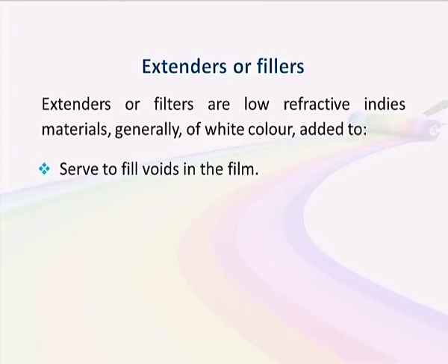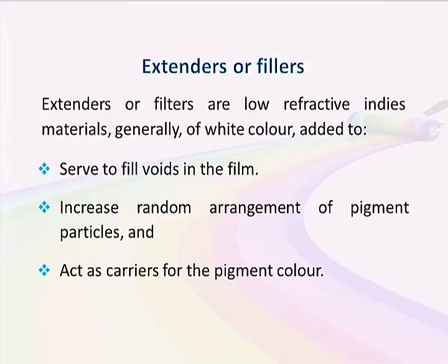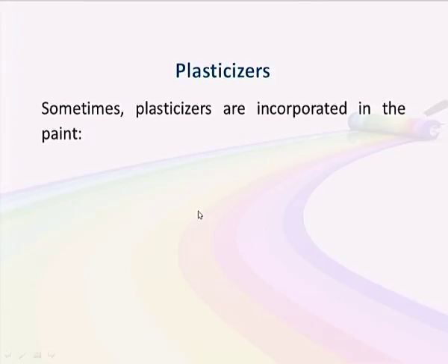Extenders serve to fill voids in the film. They increase random arrangement of pigment particles. They act as carrier for the pigment color. So, you can see how important these fillers are.